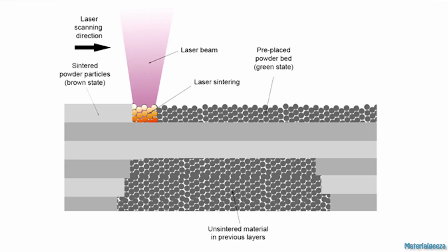There are printers out there that do print metal, and there are a few different types, but one of the more prevalent types right now is direct metal laser sintering, and it uses powdered metal and a laser that does the same thing as this printer does, except it's going through layer by layer and shooting a laser onto a powder, and it's sintering it together. So a lot of complex parts can be made like that. It's increasing in use in the aerospace industry in particular, because it allows for single body parts. So there's no welding or other seams or joints that can break.